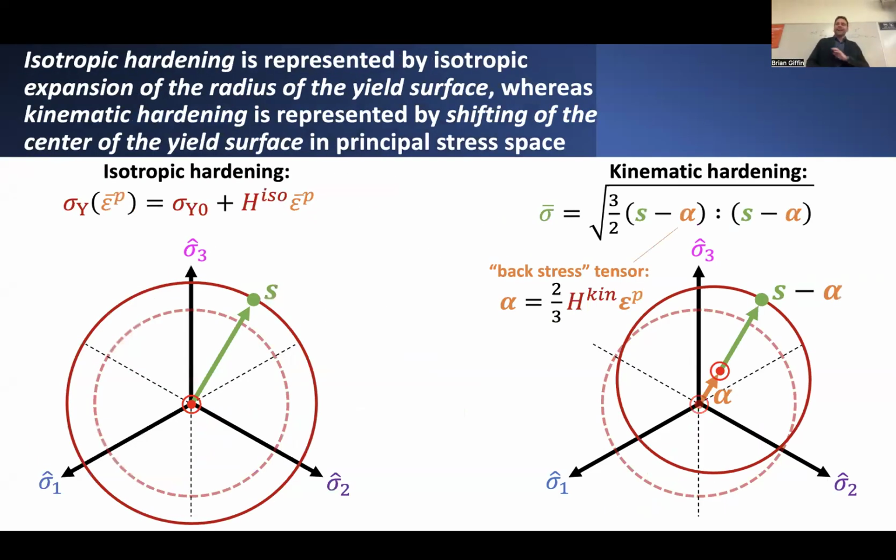And the other concepts that I want to bring back into the picture relate to how exactly we represented things like apparent increases in hardening behavior of the material as we subjected it to plastic deformations. Remember, in the one-dimensional case, we had two different ways that we could include dependence of that yield constraint equation on increases in plastic strain. There was that description of isotropic hardening, which was like saying that the yield stress itself depends on how much plastic strain has accumulated.